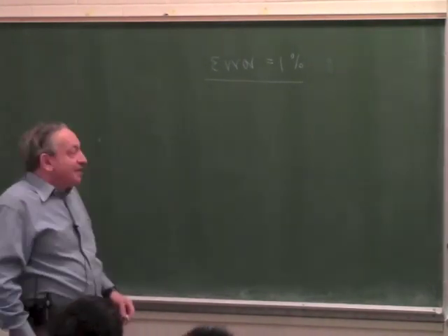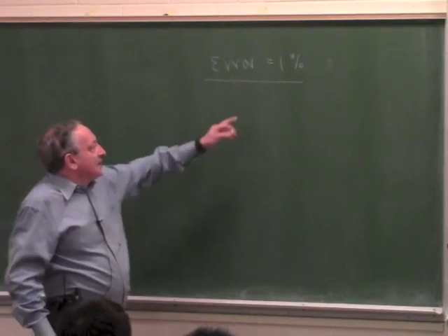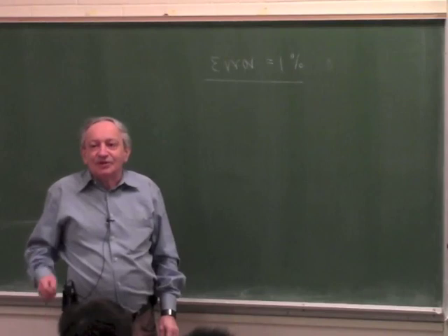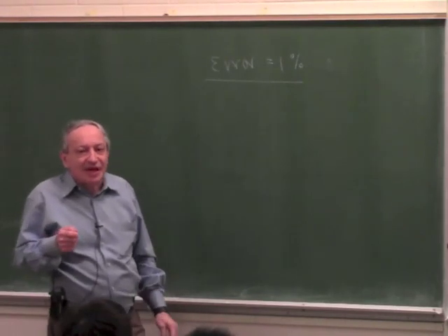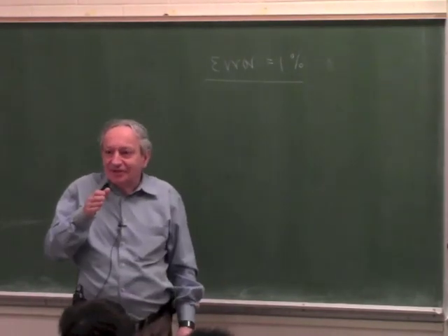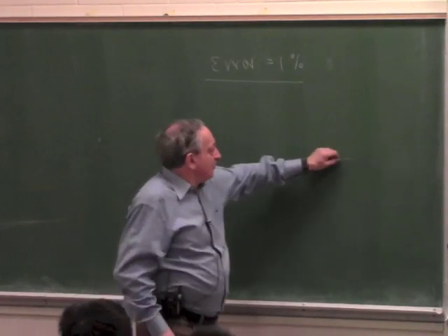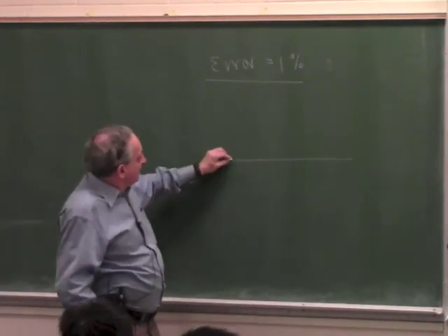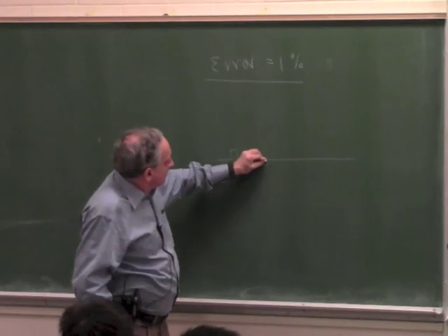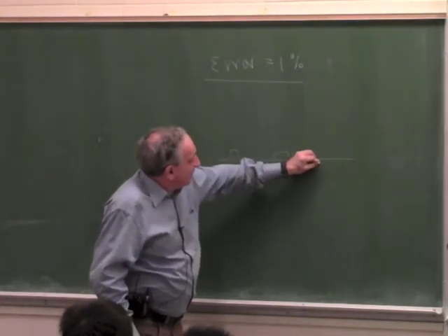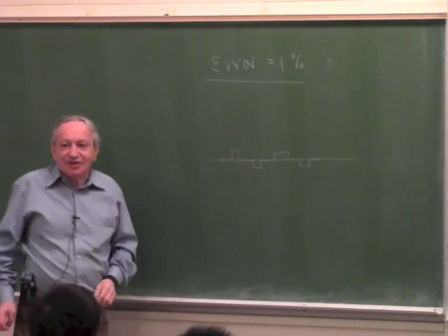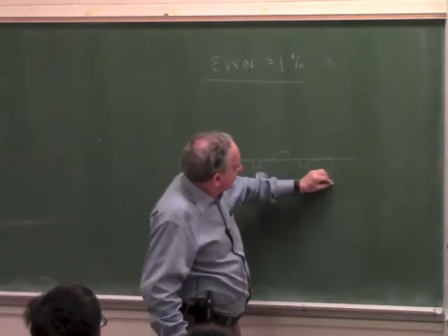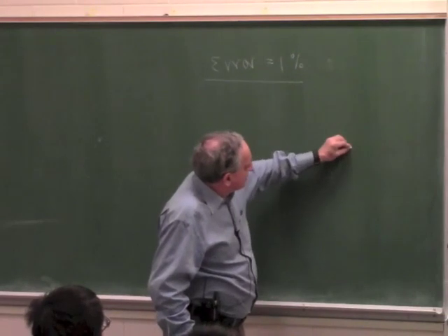But it turns out it's not true. It turns out you need at least 8 bits to achieve that. And the reason is because think of how a servo works. It always hunts around the target. And when you have a digital servo, if this is a target, the digital servo will hunt around it. It will go like this. And actually, most of the time, because of delays in the servo loop and so on, it's very common to actually have like 2-bit errors.